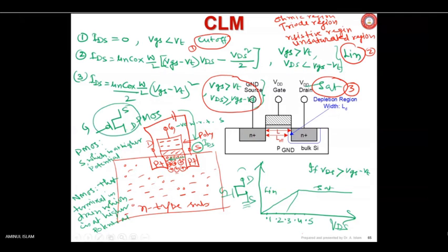They show the source at the top. It doesn't matter whether it is top or bottom, but remember that the source terminal is at higher potential than the drain. Anyway, our point was that current flows in a P MOSFET only when there is a negative gate voltage with respect to source.